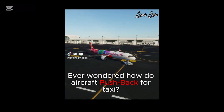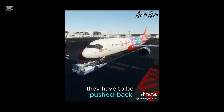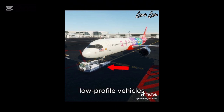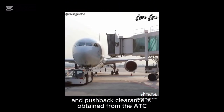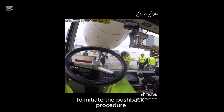Ever wondered how aircraft push back for taxi? Before an aircraft can taxi to the runway for takeoff, they have to be pushed back from the gate to the taxiway. Pushback tugs are special low-profile vehicles that connect to the nose wheel of the aircraft during a pushback procedure. Once the aerobridge is disconnected and pushback clearance is obtained from air traffic control, pilots will then communicate with the ramp agents to initiate the pushback procedure.